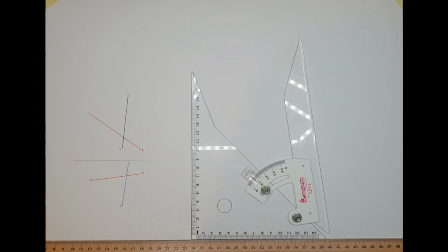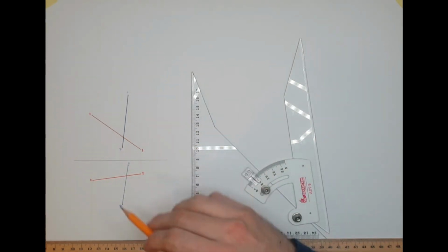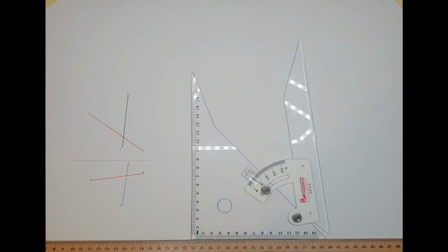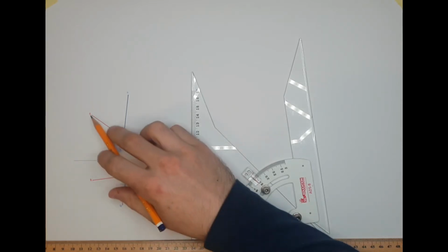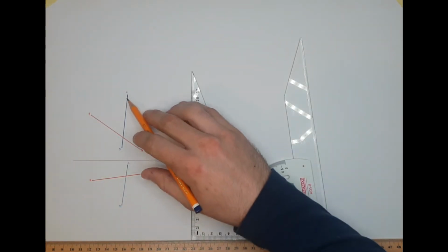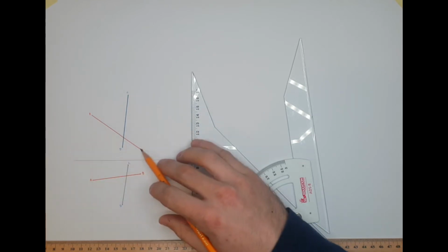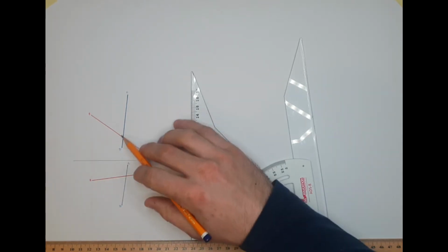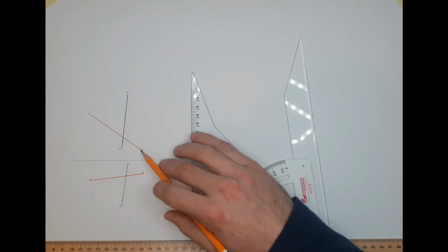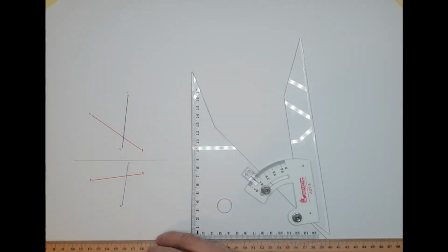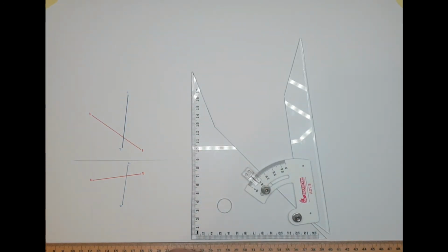Let's get cracking. I want to create my plane. Create a plane that contains one of the lines. It contains the line AB in this case. Now, this can sometimes be the difficult part of the question because there's 4 possible ways to go. It can contain AB and has to be parallel to CD. So I can go down and across horizontal. Or I can contain AB and parallel by going up and across. Or I can contain CD, and look, there's 4 different ways to go. You can contain any line and work from any end, and sometimes it's no problem, you can do it anyway, and sometimes it might not fit in the page.